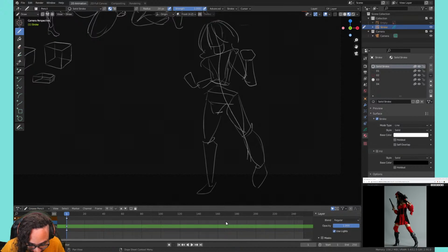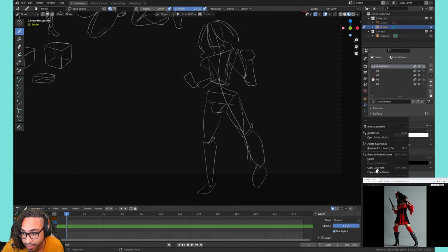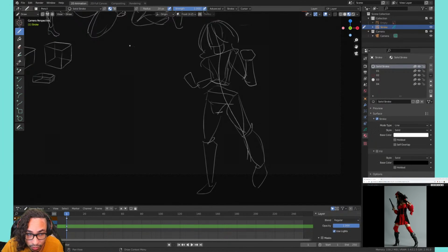One thing that blew my mind recently was finding out that if you right click any tool on the left bar, you can assign a hotkey and it's super easy. Yeah, that's actually really great. You can do that with anything, I think. You can also have a quick menu. If you hit Q, these are your favorites. If you right click on this and click add to favorites, you can add it. When you hit Q, this will be your favorites bar, and you can have all the buttons that you use all the time here by just hitting Q. That's actually pretty neat.